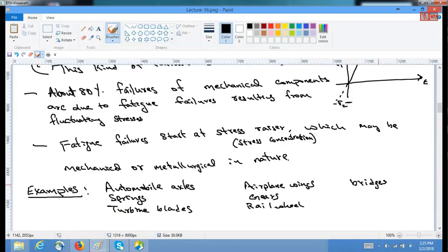So this is the kind of thing. In today's lecture we'll understand what fatigue is and how to create a fluctuating load, and what the types of nomenclature involved in the fluctuating stress components are. We'll also talk about fatigue strength, the SN curve, endurance limit, and other important topics that are required for mechanical component design for fatigue cases.